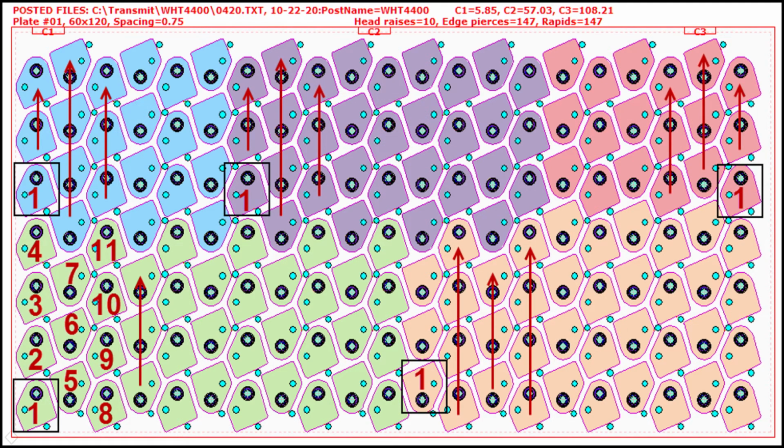Sequencing individual parts within each group. Once the groups are detected, the software sequences the individual parts within each group. The punching sequence is done by snaking up and down within each group. Having punched the parts within a group, the parts are sequenced in one direction to cut the parts in the group toward the clamps.